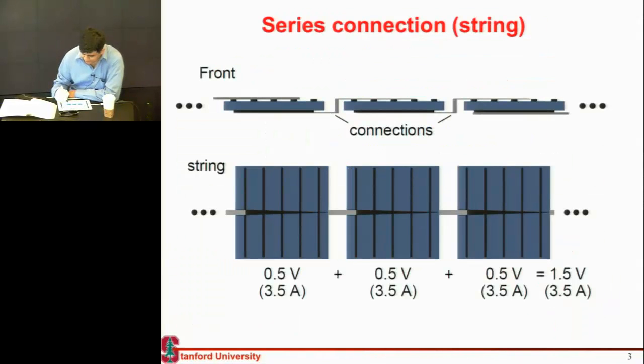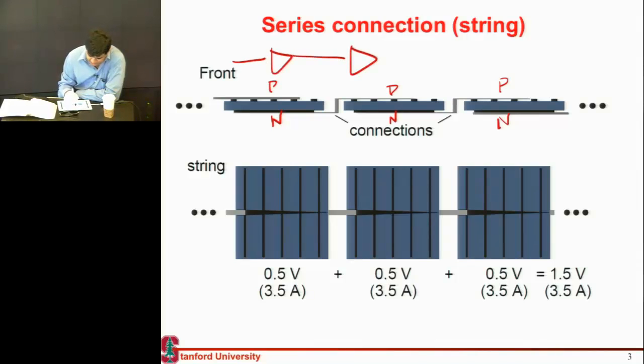So picking up from where we left off in the class on Wednesday, we had made these individual solar cells, and these had the p-type contacts on the top and the n-type contact on the bottom. Now when I assemble them in a module, I need to somehow connect these diodes in series with each other. So the way I do that is I take this, which is usually called the bus bar. So this is the bus bar for each of the solar cells, and it has many of these fingers, and each of them are collecting the carriers which are generated.